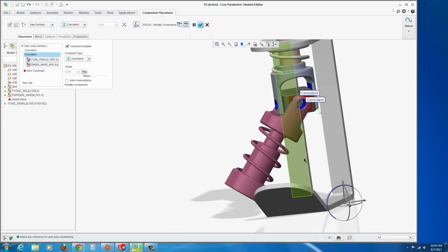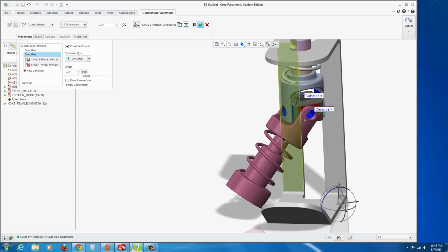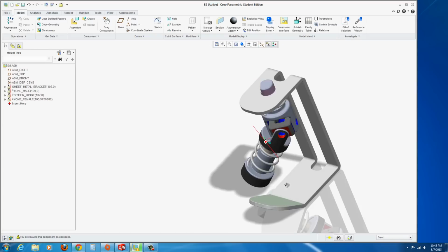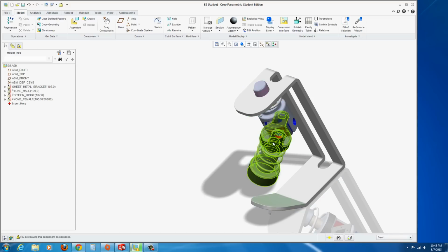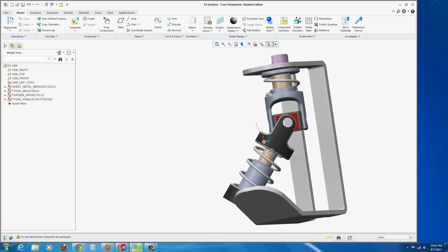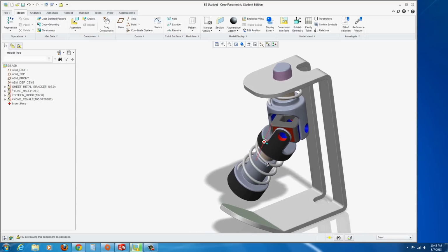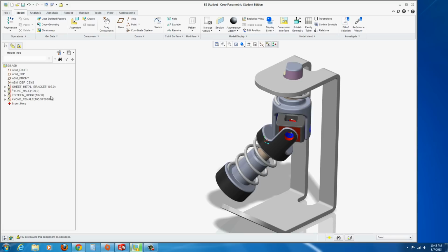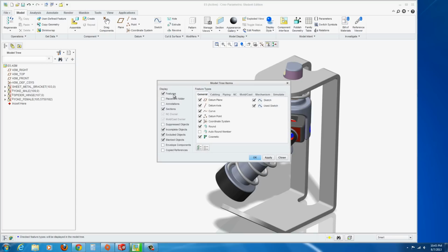There we have it. Now it's not quite done yet, but let's say by accident you hit enter or the green check mark. And then you realize, oh, we never mounted it down to this bottom surface here yet. Anytime you have to edit something inside CREO, this is all you do. You find the feature in the tree. Remember, these don't always show up. Remember, the little hammer, tree filter, you might have to turn on the features to see them.